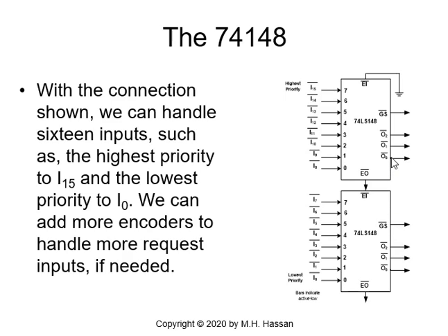Those outputs, output 0, output 1, output 2, are inverted, and can represent the code from here. So if this one is active, which is active 0, the output definitely will be equivalent to the code 0, so what you will get is 0, 0, 0, okay?